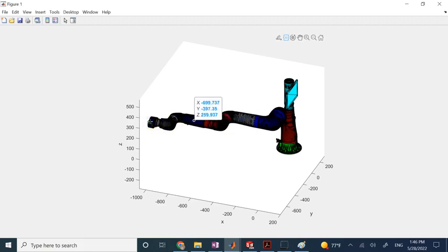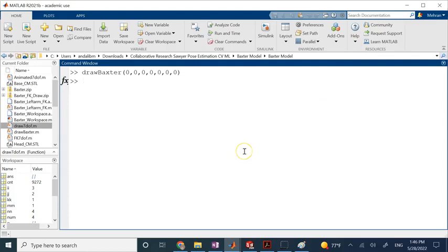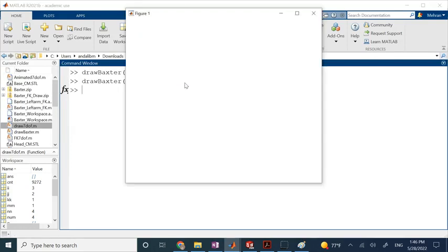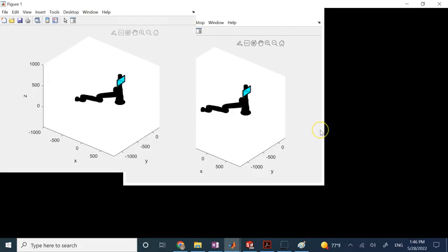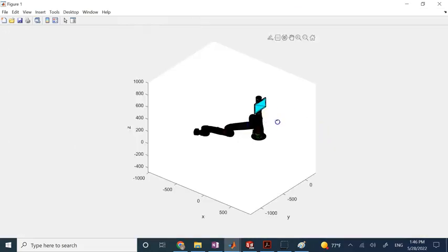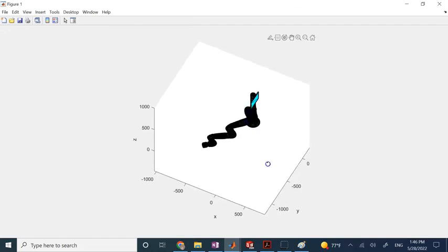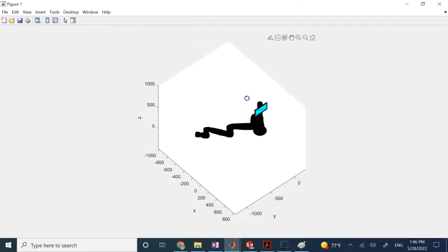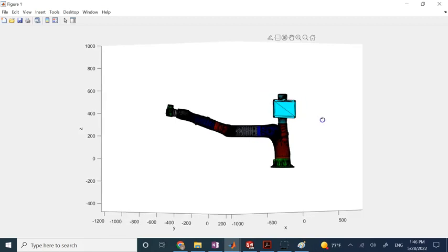If you want, you can click on this end effector and so on. Good. So this function, if you now use a separate set of joints, let's say you want to rotate the first joint by 50 degrees, the fourth joint by 20 degrees, the sixth joint by 10 degrees, and this one maybe by 60 degrees, then it can replot the robot at those values for you, right? So now you clearly can see how the robot has changed its configuration. Right? So here we go.